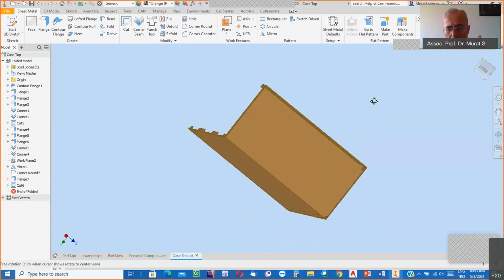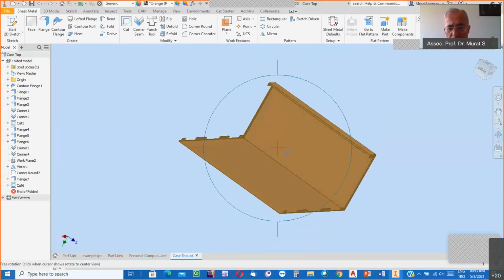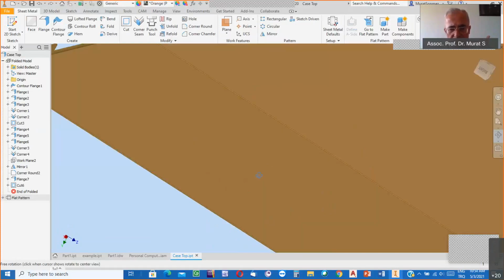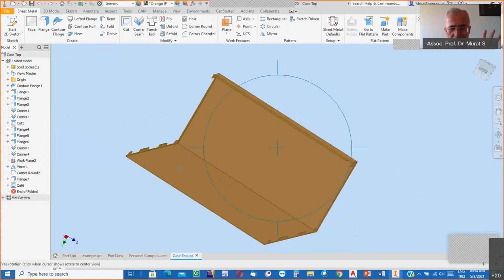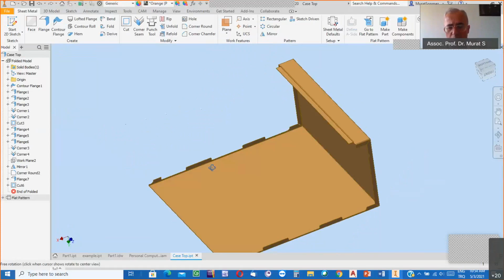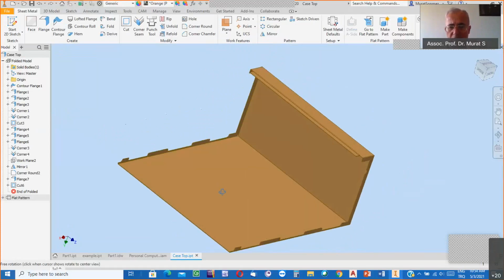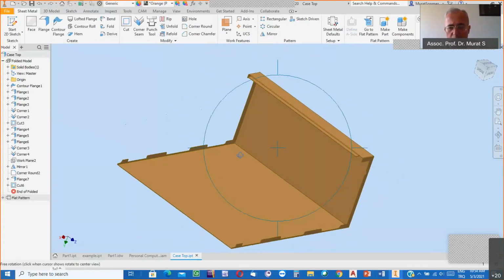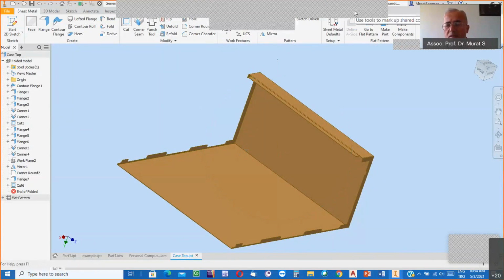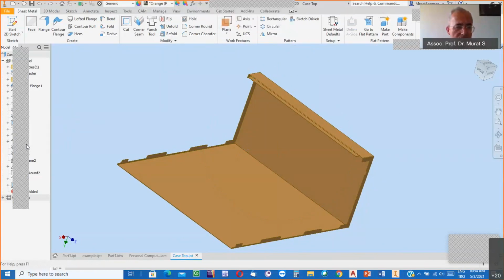Well, this is, you see, a sheet metal work. It's a sheet metal component. Its thickness is the same. Well, here, all the parts, okay? And well, it has been folded. Initially, it was a flat sheet, but after folding, the folding lines were annotated in this color. Along this edge, it has been folded. Along this edge, folded, and here another edge to fold, one more edge, and so on. After the folding stage, we have the component in this final shape and final size.